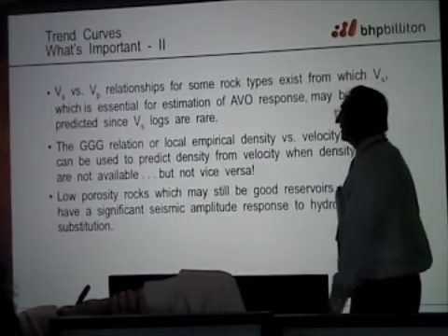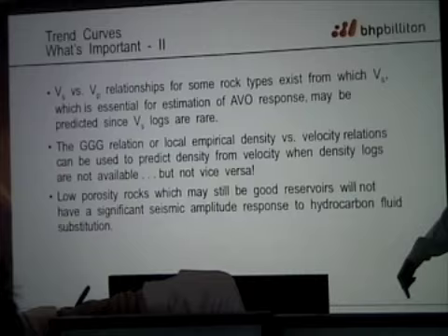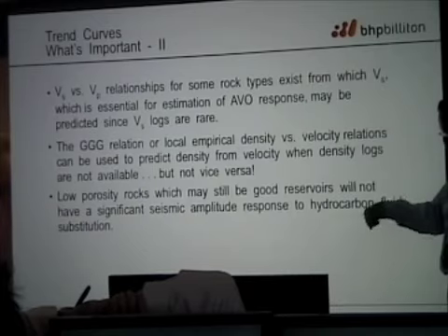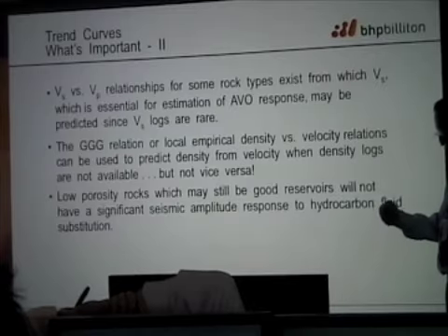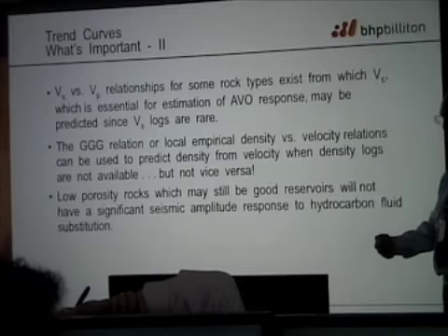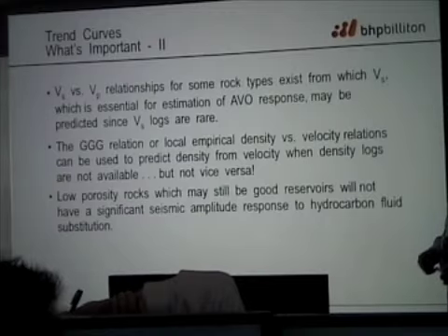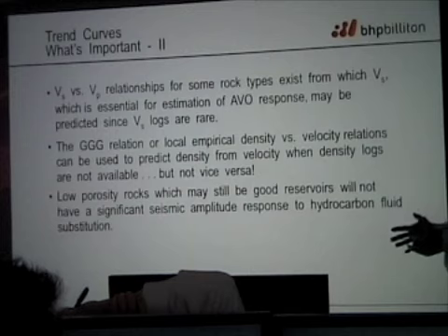It turns out that when you're going vertical, there's a birefringence. That means a different propagation velocity for shear waves that are polarized in one of the 2 principal directions. What determines the principal directions is anisotropy in the basin. That can typically be a stress anisotropy.